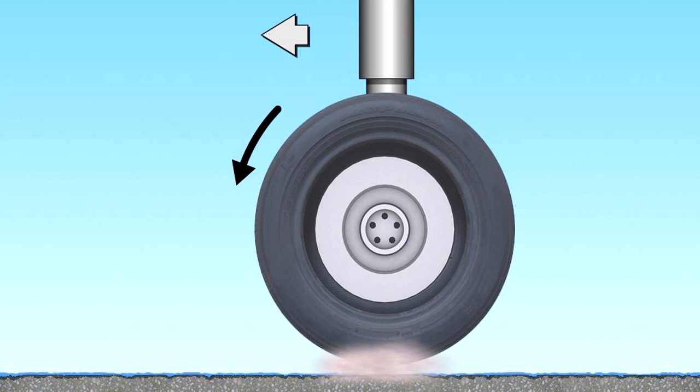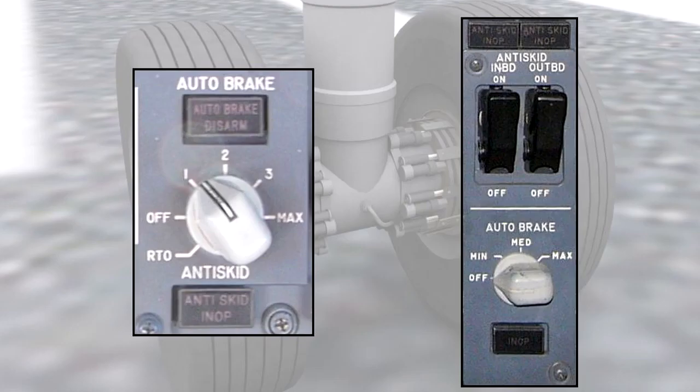The steam heat reverts the rubber to a black gummy deposit on the runway. Once started, reverted rubber skidding will persist down to very low speeds, virtually until the aircraft comes to rest. During the skid, there is no steering capability and the braking effect is almost nil. Reverted rubber hydroplaning is greatly reduced in modern aeroplanes due to the standardization of advanced anti-skid braking systems, which prevent wheel lock-up.